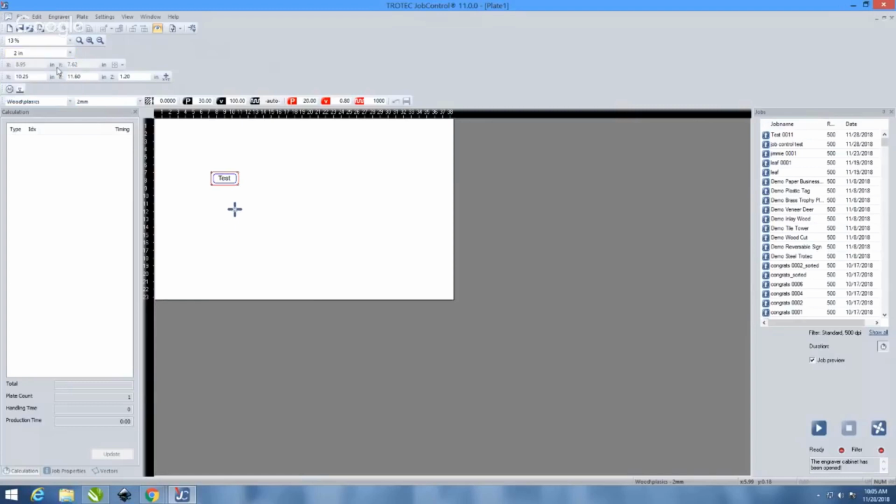If you don't have the right lens in, what possibly could happen is when you go to focus your laser, it'll think that it has a different lens in it, so it may crash into the material that you're trying to focus on. For instance, if you're trying to focus with a 1.5-inch lens, but the laser thinks you have a 2-inch lens in there, or sorry, vice versa, it might crash into your materials.